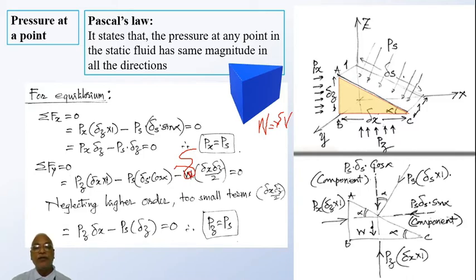So gamma multiplied by the volume term, because what is the volume of this element? It is the area of the front face multiplied by 1. So volume is equal to front face area, that is delta x into delta z by 2, multiplied by the third dimension, which is unity.